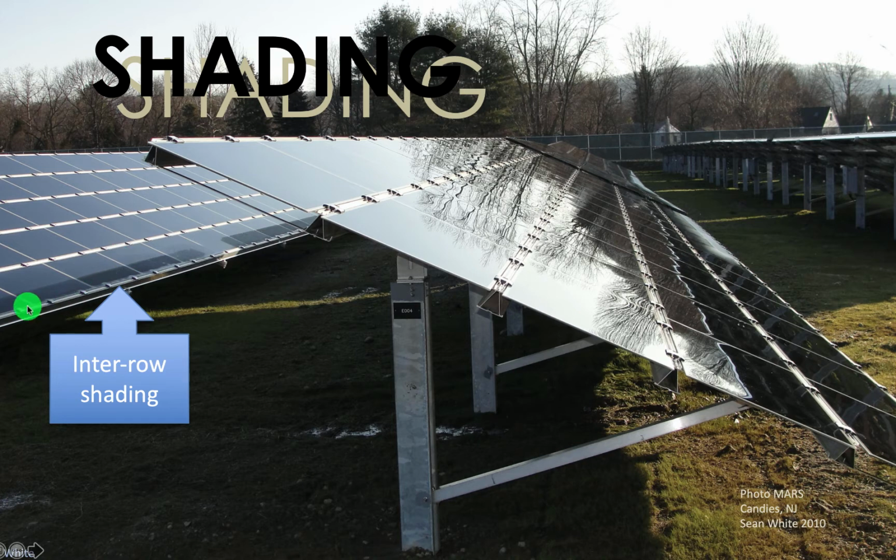This particular type of thin film is called cadmium telluride. We're going to hit this in the next module when we talk about PV module fundamentals. What we have here is called interrow shading, and that's shading between rows. This was a winter day in the morning. Remember, it was very cold, and we had this row shading this row. There's two different ways that we could get rid of this shading. We could decrease the tilt angle, or we could move the rows further apart.